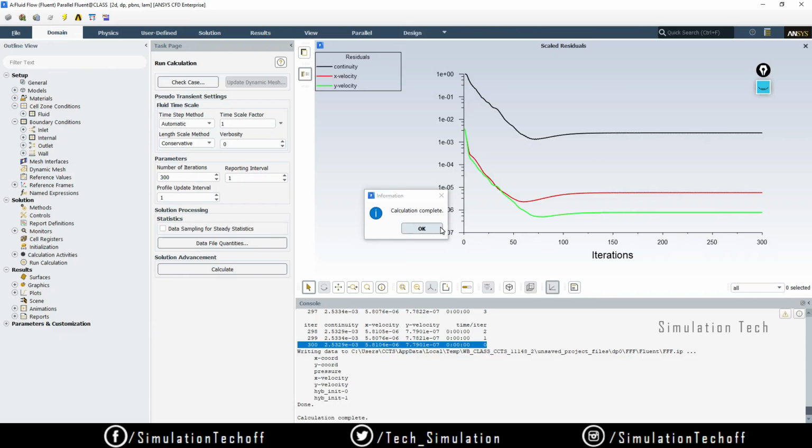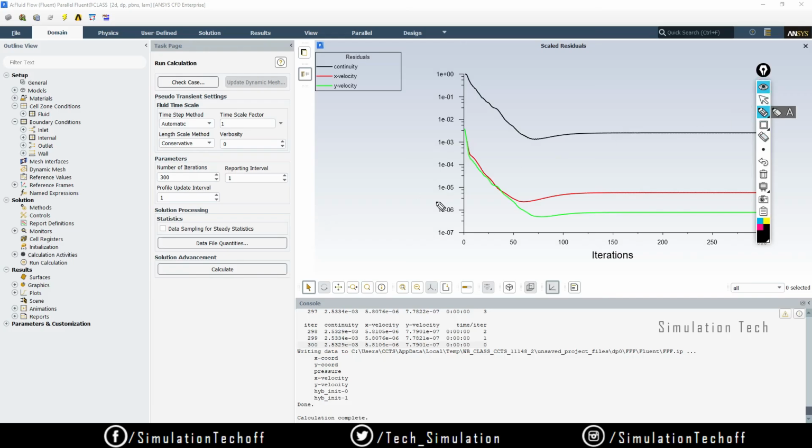There might be a lot of reasons why the problem is not converged. So how can I make sure that my problem is converged or not? All the values should be here, right? The difference between the two numbers should be below 10 to the power of minus 6. It's a very minimum thing, like 0.00. That difference will be allowed. So when the two previous values are equal, the problem is automatically converged.